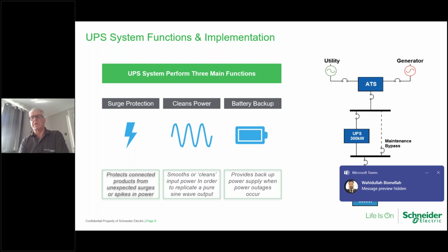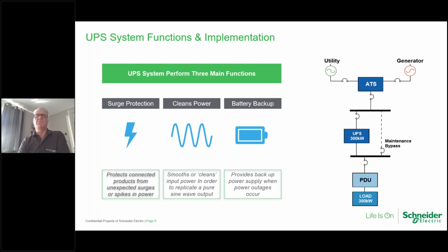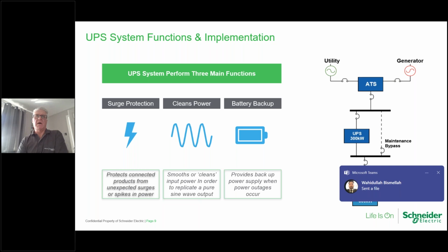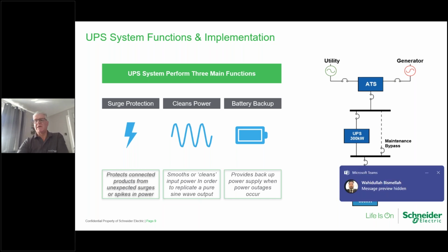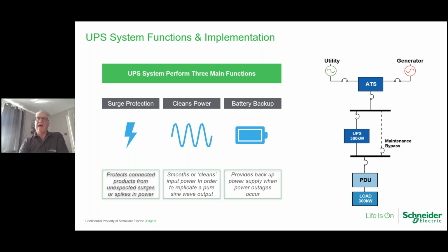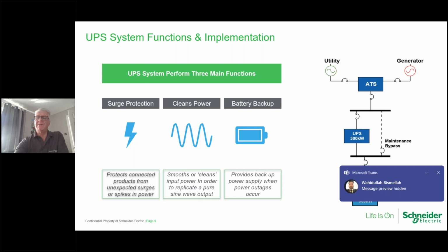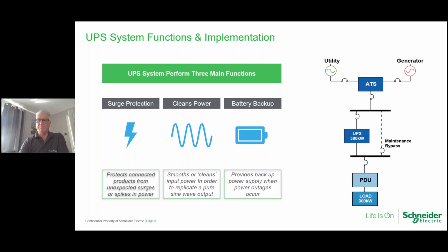And of course, the other part is that we will often have, in addition to the UPS, a generator. A generator will sit there. So we have a utility supply, but during the switching of the utility to the generator restart, we have an ATS that switches those supplies. The UPS will help support that switching. So the switch from utility to the generator will be covered by the UPS, and we're then back up and running.